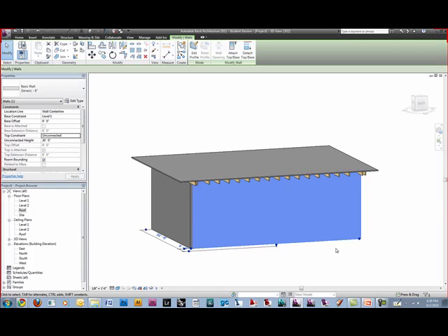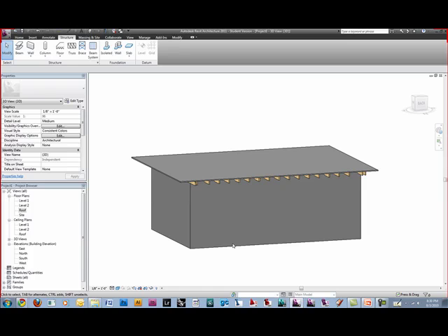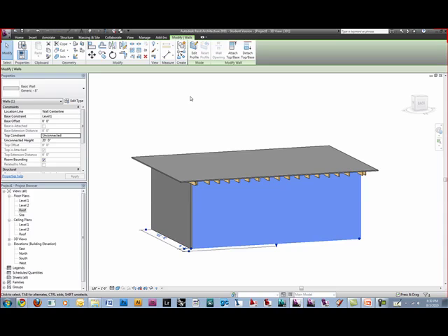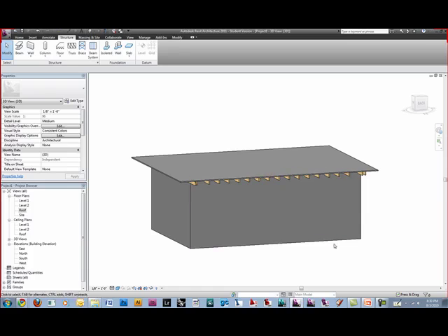We're going to draw in curtain grids, create mullions from it, something simple, and then show you how you can change that curtain glass into other materials really quickly. Sometimes you just want to do an insert inside a curtain grid, say if you're repeating a pattern of brick or something with the glass, to make it look a little nicer.